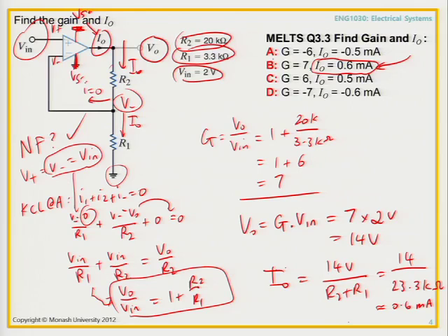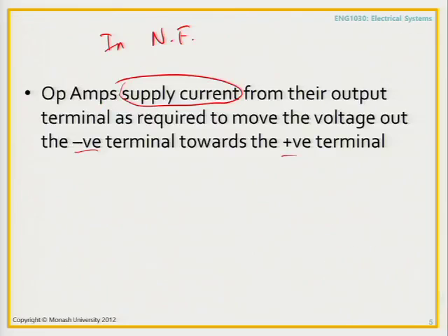So you connect some external voltage to those supply terminals, and that's really where the current from the op amp comes from. But the op amp will do smart things to get the exact amount of current required to make V minus equal to V plus. And that's what is really happening. Okay?